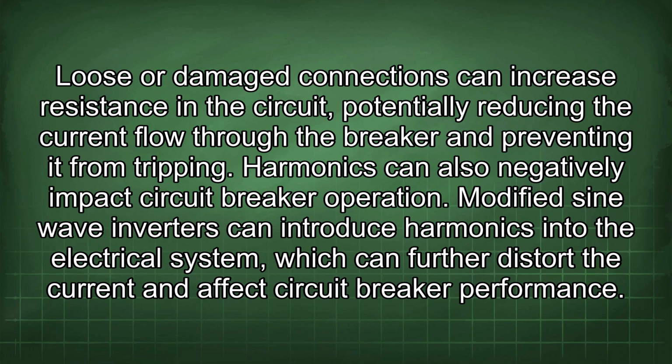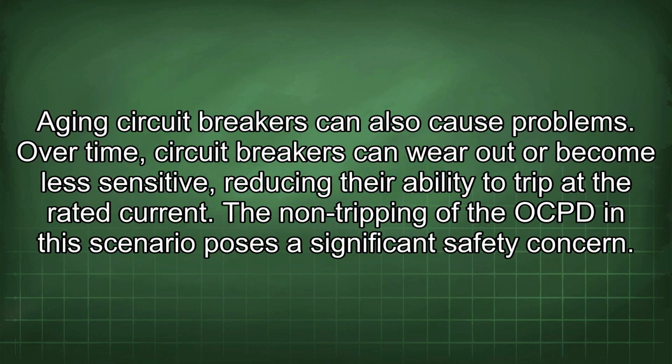Modified sine wave inverters can introduce harmonics into the electrical system, which can further distort the currents that affect circuit breaker performance. Aging circuit breakers can also cause problems. Over time, circuit breakers can wear out or become less sensitive, reducing their ability to trip at the rated current.